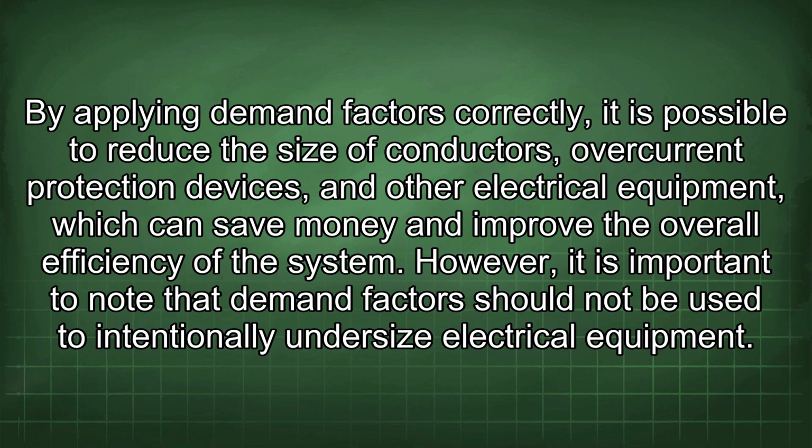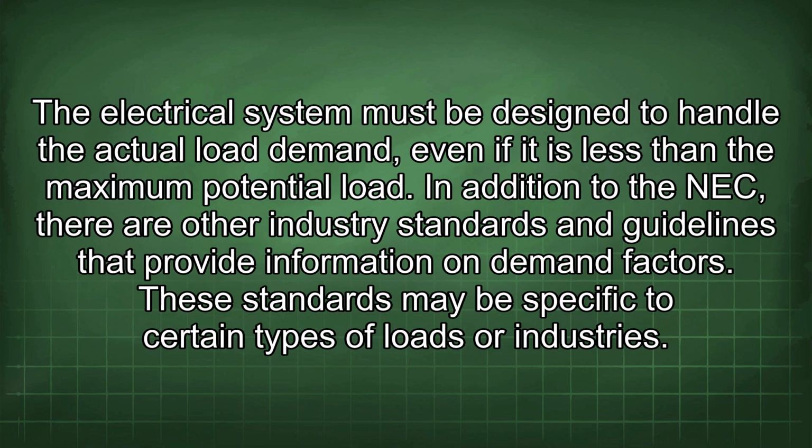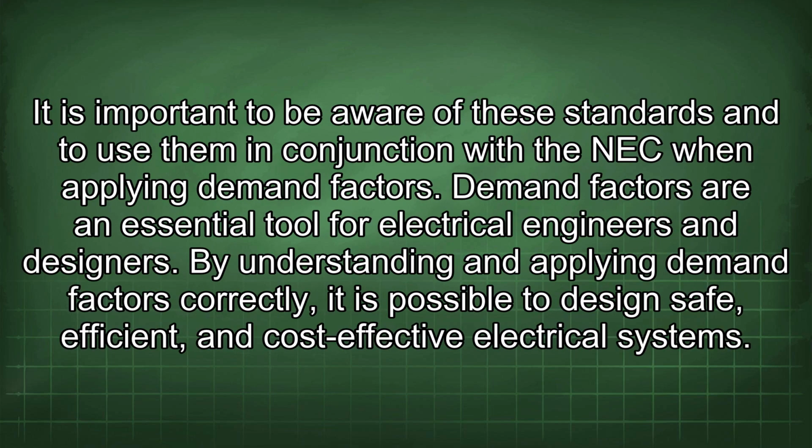However, it is important to note that demand factors should not be used to intentionally undersize electrical equipment. The electrical system must be designed to handle the actual load demand, even if it is less than the maximum potential load. In addition to the NEC, there are other industry standards and guidelines that provide information on demand factors. These standards may be specific to certain types of loads or industries.